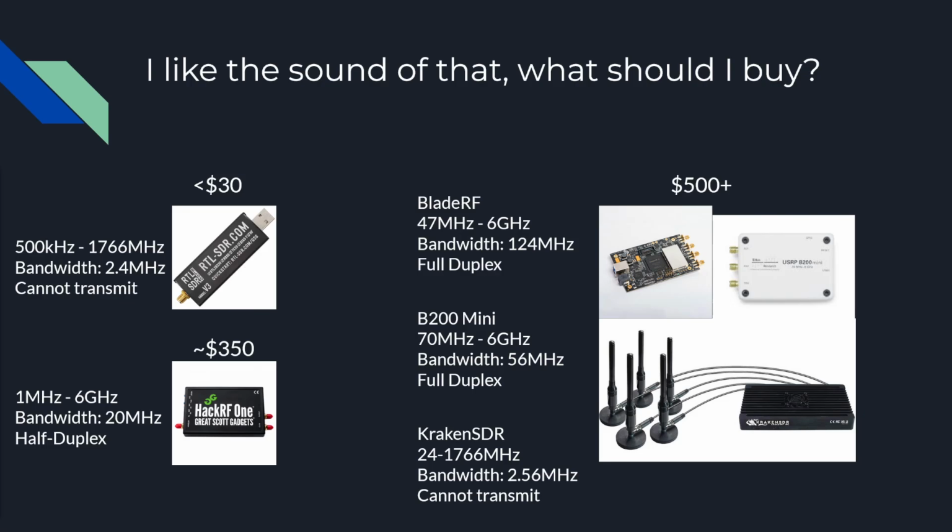I don't even know if there's really a ton of software defined radios that would help for that, but low band you could check out for sure. Yeah, millimeter wave, like the N260 stuff, to my knowledge I don't know of any software defined radios that would even get up to those frequencies. And then 3.7 gigahertz would be just fine. You could probably do the low band and the mid bands with HackRF or BladeRF or B200s.